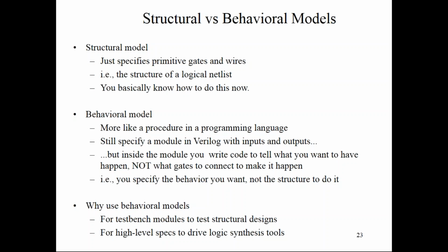For example, if I want to design a multiplexer, consider a 4x1 multiplexer. In that, two selection lines and four inputs are there. In the case of structural modeling, I am describing the hardware functionality. That means how many AND gates or NAND gates there are, how many NOT gates, and how many inputs and outputs there are.